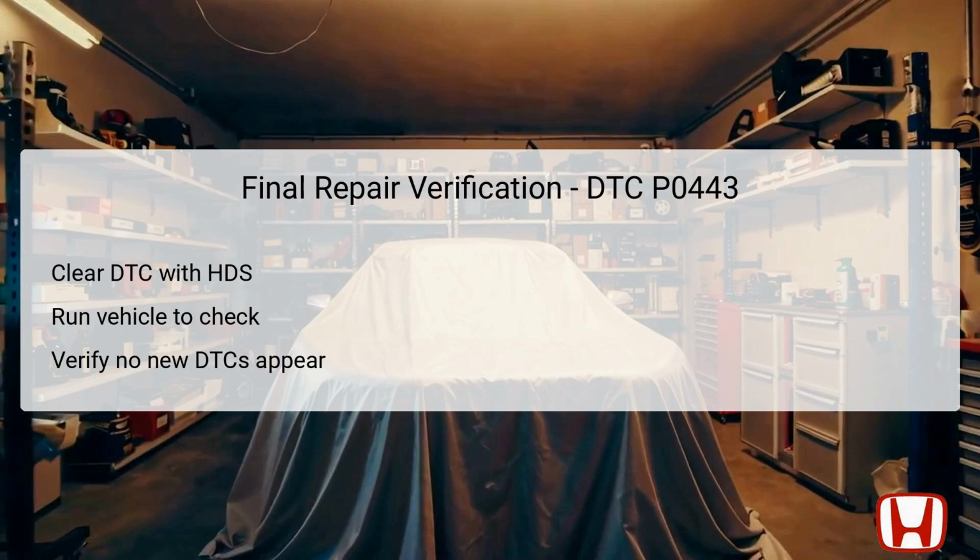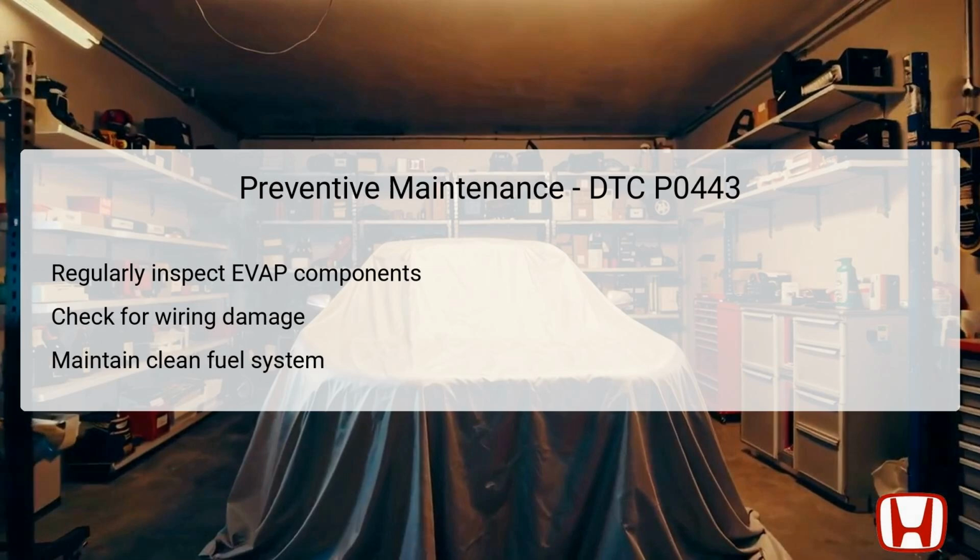To preemptively address issues associated with the EVAP Canister Purge valve and avoid DTC P0443 in the future, performing routine maintenance is essential. Regular inspections of the EVAP components will help catch any physical wear or damage before it leads to failure. Additionally, inspect the wiring connections to ensure there's no fraying, corrosion, or other issues that could affect functionality.